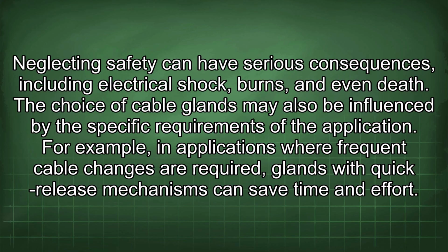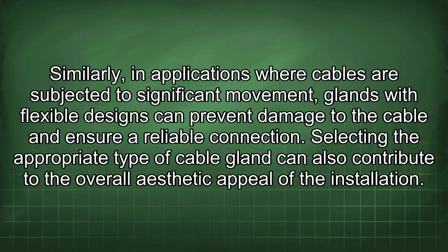The choice of cable glands may also be influenced by the specific requirements of the application. For example, in applications where frequent cable changes are required, glands with quick release mechanisms can save time and effort. Similarly, in applications where cables are subjected to significant movement, glands with flexible designs can prevent damage to the cable and ensure a reliable connection.